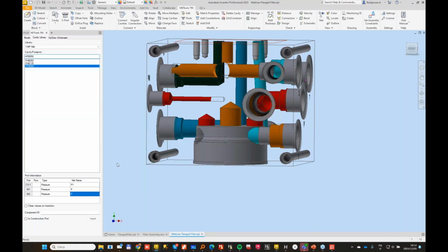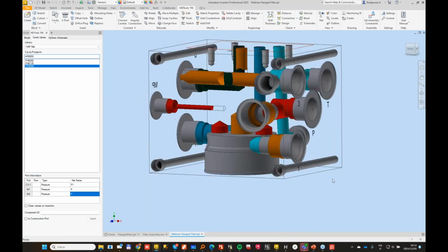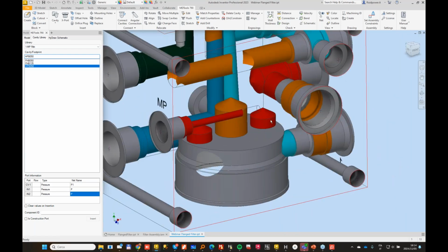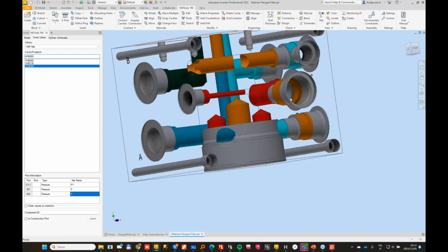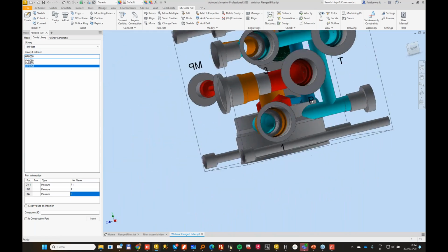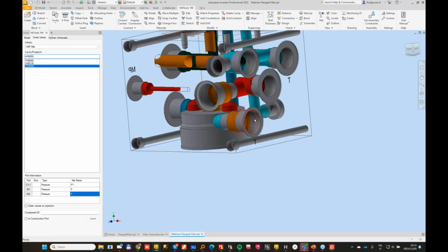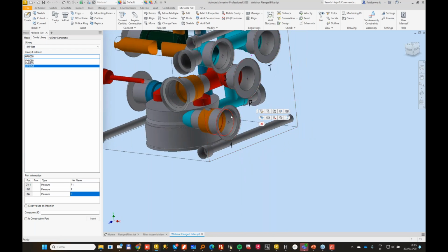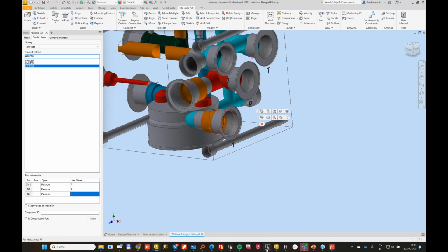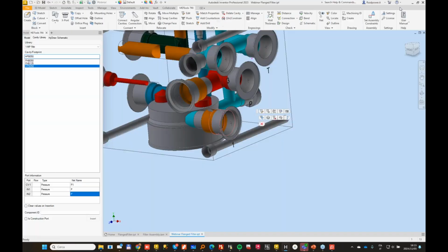By doing this, of course, I remove a cavity that was not in a good position. I also get all the red part, so all the inlet on one side, which is good because now the connection will be very, very easy. This valve cannot be in a good position here. This is a solenoid valve, so it's the normally open valve as a bypass. It was a valve number 1 here.